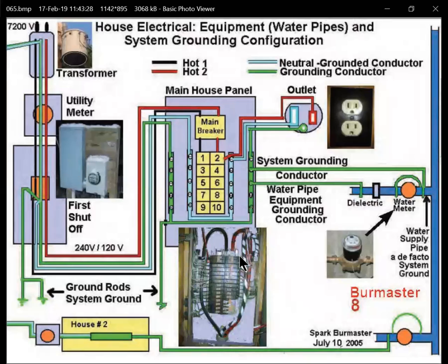But anyway, this is an example of what a main panel looks like. This is kind of a crude version, because the main thing I was trying to illustrate with this particular drawing is this issue: if wires come into the panel and they're greatly separated inside the panel, then the panel itself gives off big magnetic fields. So that's why we don't like this particular configuration of showing separated wires. And then you see the ground wire continues here, goes all the way out to here. And then we have another wire.